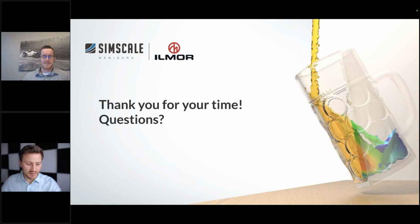Yeah. Nice. There's another question that I'll answer about the SimScale side. Someone asked about parallel simulations: can you run all of the different pressures in parallel? Yes, totally. In SimScale, you have no limit on the number of simulations that you can run in parallel. For the piston simulation, you could set that up as a parametric run where you sweep through maybe 100 different pressures and run all those simulations at the same time. Each simulation is started on its own dedicated AWS instance in the cloud, and then you get the results when it finishes.